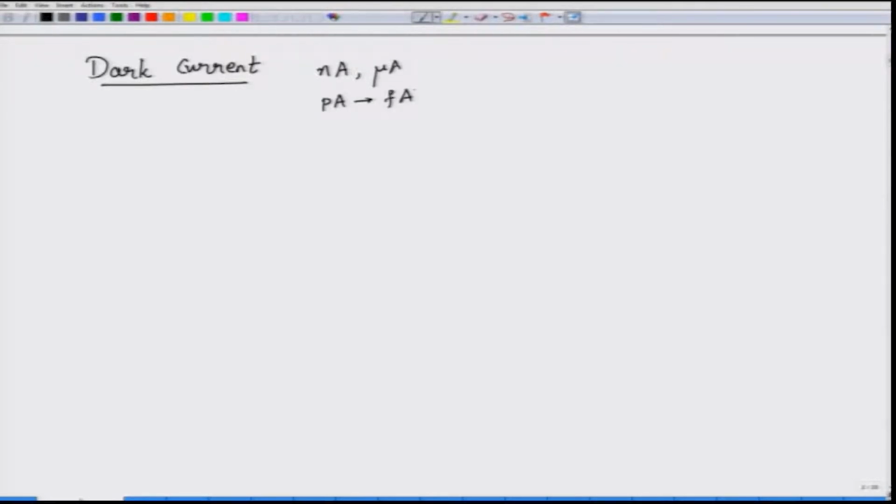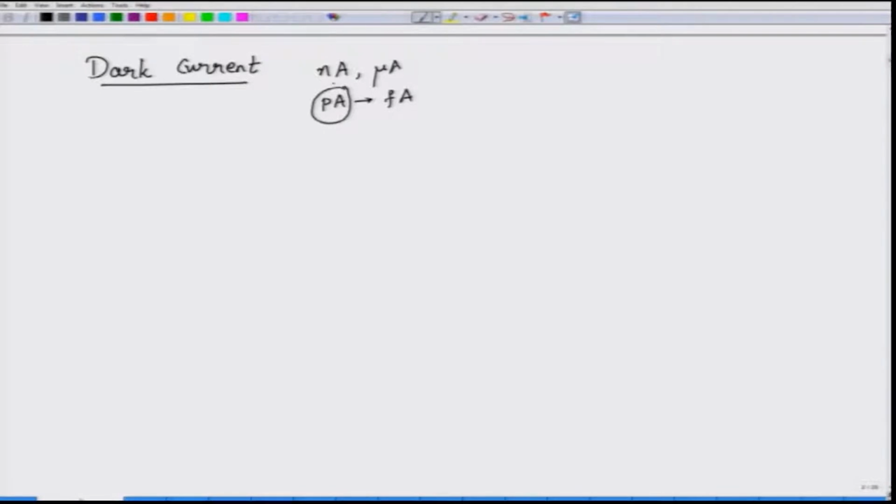So this component is quite negligible when you are working with very good photodiodes, especially in telecom applications. You are now able to obtain picoampere dark current photodiodes. So this is for the dark current. There are three reasons why you get dark current, although evaluating them is very difficult. One is the diffusion of minority carriers generated because of thermal agitation. As I said, thermally generated electron hole pairs will drift under the application of the reverse bias voltage, causing a minority carrier diffusion current, which causes dark current.